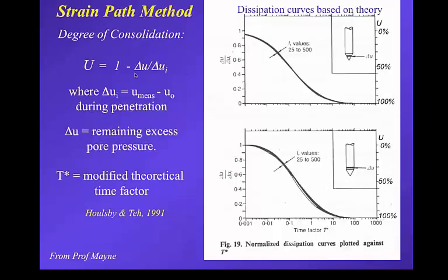And it generally fits a simple soil behavior where you have large excess pore pressures and they monotonically decay with time. And often it's applied at the 50% dissipation, and that time is often referred to as the T50, so it's a single point, and so that means there's a simple chart that you just take this T50 and go to the interpretation. And you need an estimate of this rigidity index, and it can handle different locations, and you get this very simple chart. And so this is what the theory produces.